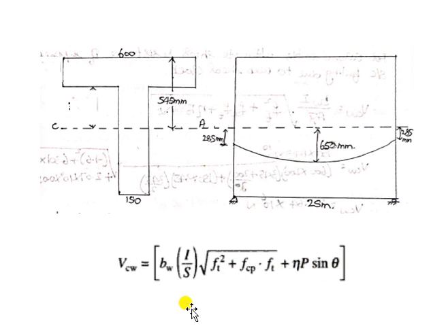As I told you in the previous session, to calculate the ultimate resistance due to shear, we have two equations. So the shear resistance can be calculated using this equation, or else we can also consider 0.67 d instead of this I by S. So let us consider this formula. We should select the formula as per the given data in the question.